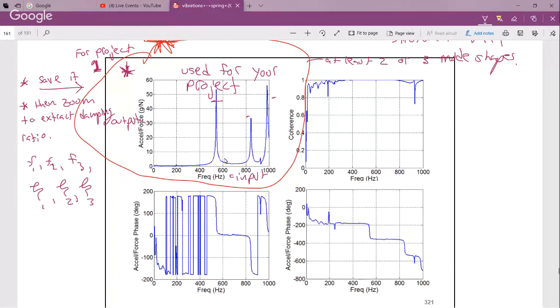There are reasons, because I'm interested in the AC. But the other thing is that 1,000 pounds, that huge DC, would take up most of my input range, and the fluctuations would get lost in the noise. You know what I'm saying? That's why we have that option. That's the AC/DC setting that exists on the input of any dynamic analyzer. Bias is something special that we have in vibration. All right, so that's it for our input channel.